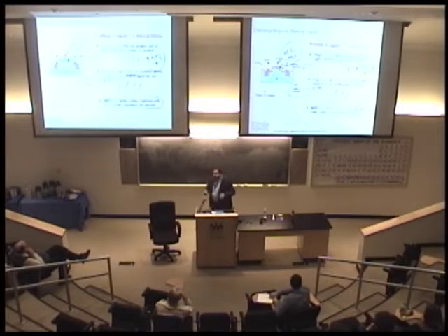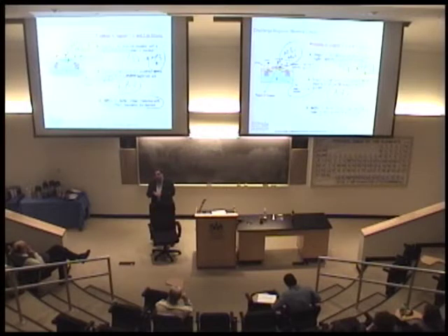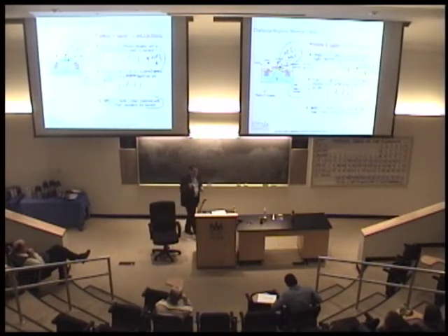And the reason is that when you contact nickel silicide as a conducting element with the hafnium dioxide, the junction resistance goes down, okay? Otherwise, if you try to push the copper onto hafnium dioxide, there will be a huge junction resistance. The transistor is not going to work. Okay? So if you change one small part of the transistor, you're going to play with a lot of materials. These are the material-based challenges. You want to make these things as small as possible, but every time you try to do something, a new problem comes up. Okay?